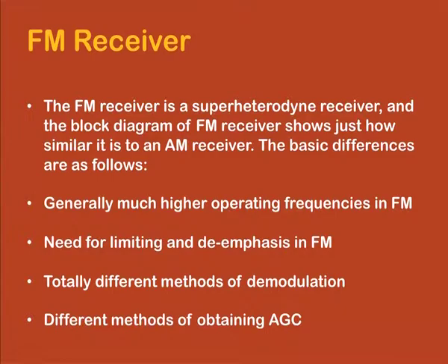So, a good compromise for interference performance would be if we can have a signal modulated as FM at lower frequencies and modulated as PM at higher frequencies. This can be achieved by using a simple pre-emphasis circuit at the transmitter and de-emphasis circuit at the receiver.